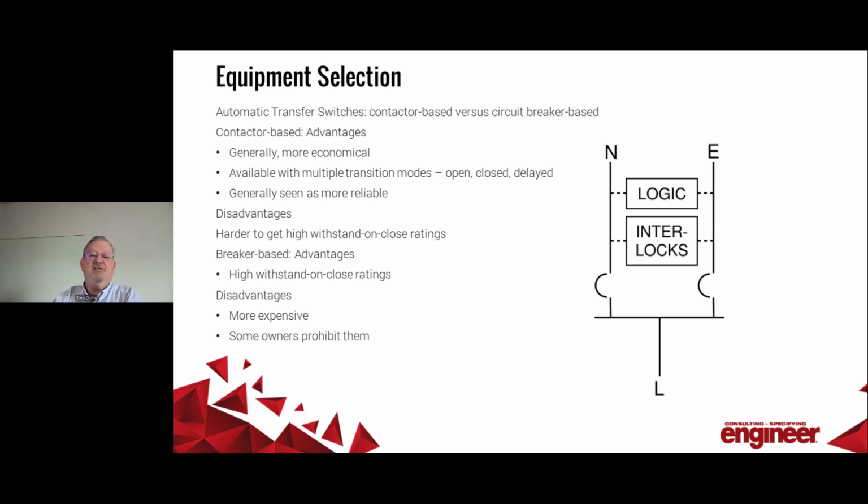Contactor-based switches are usually cheaper, and they're often seen as more reliable. They're also readily available with multiple transition modes like open transition, closed, or maybe delayed transition. The fault current and withstand ratings are generally lower for these switches than for breaker-based switches. Circuit breaker switches have fault withstand that's equal to that of their breakers, and those can be very, very high.